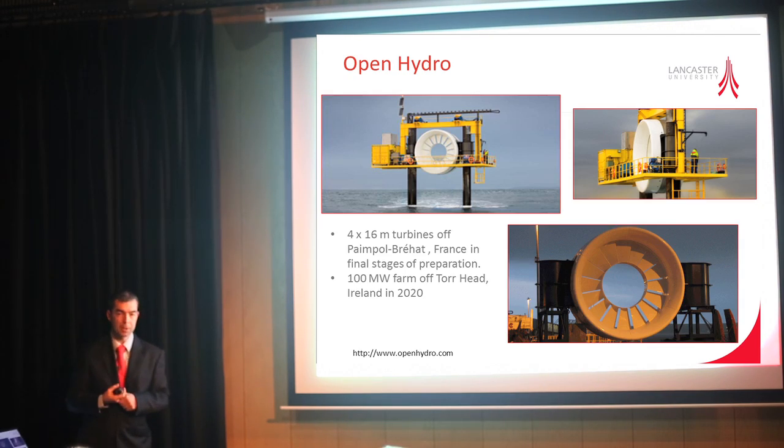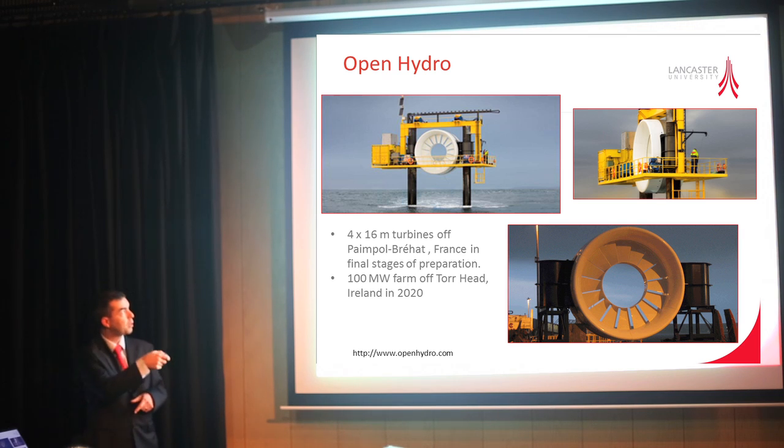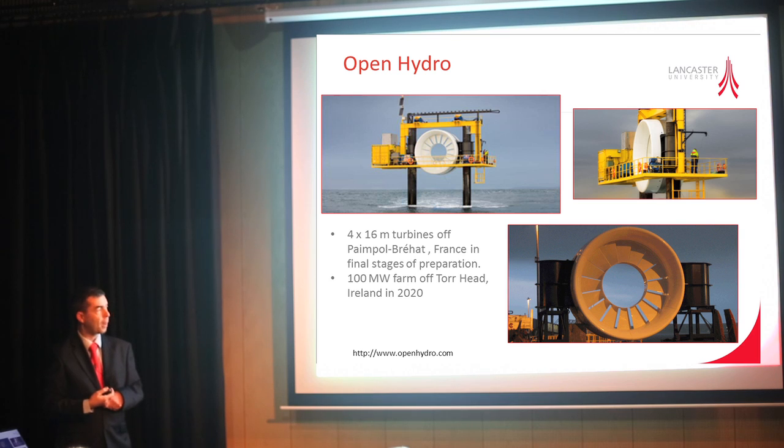Open Hydro, slightly different in terms of the concept. Rather than work on a central shaft and have that rotate, you use the outer side of your rotor as your stator, and you can generate the electrical field from that rotating in terms of magnets. The middle of the turbine doesn't really move very fast anyway, so you don't get much power output from the centre of it. And they've had it installed at EMEC, the European Marine Energy Centre, up in Orkney. They're also preparing off the Irish coast. They're an Irish-based firm, so it makes sense for them to start there, as well as a number of units in the French coastline. Okay, so moving forwards with their designs.